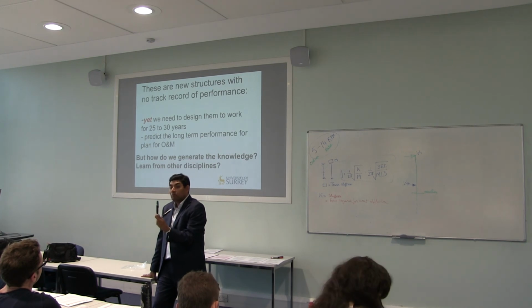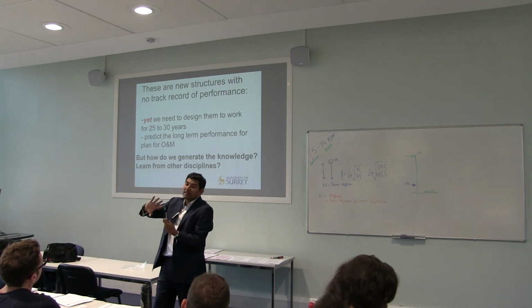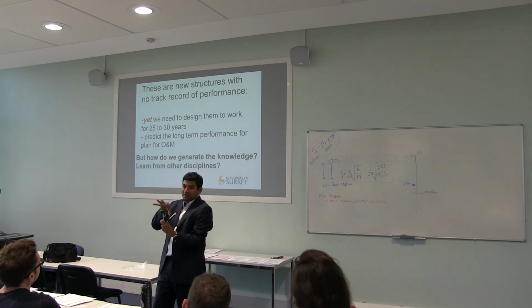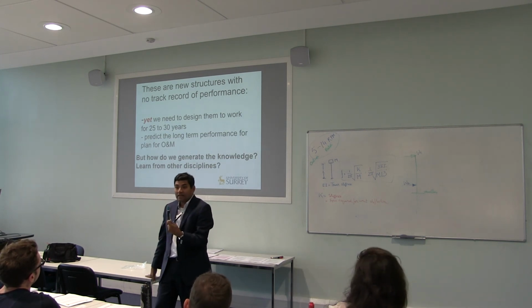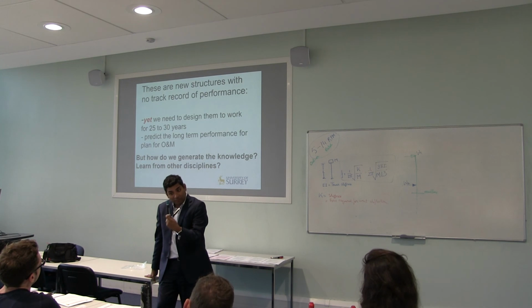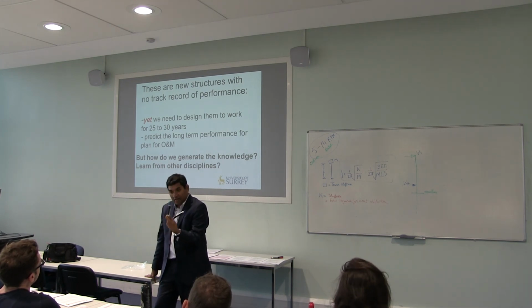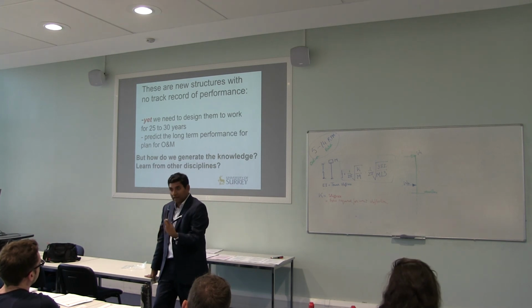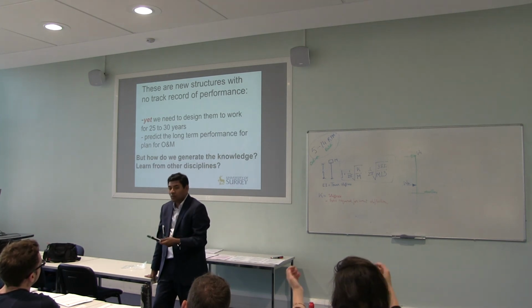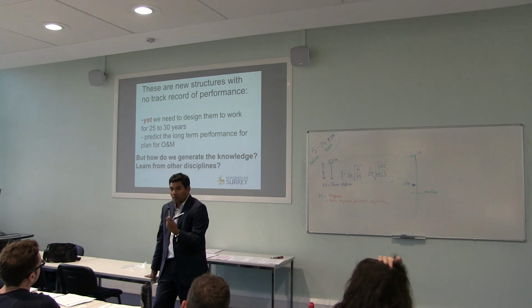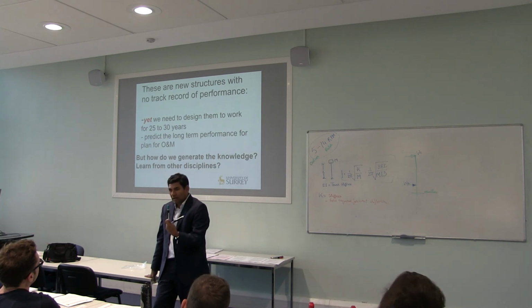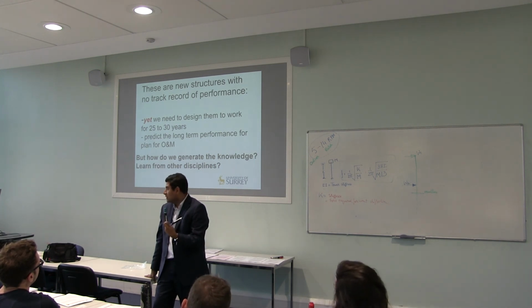You will start to have a big imbalance, because the blade has to be symmetric, perfectly aligned. If the blade starts to crack, then you start to see more vibration. If it vibrates, it can set off resonance. Then it can have a failure. If it fails, you have to change it. So what's the option? You have monitored them. The blade cracks, fine. But you have to change a blade.